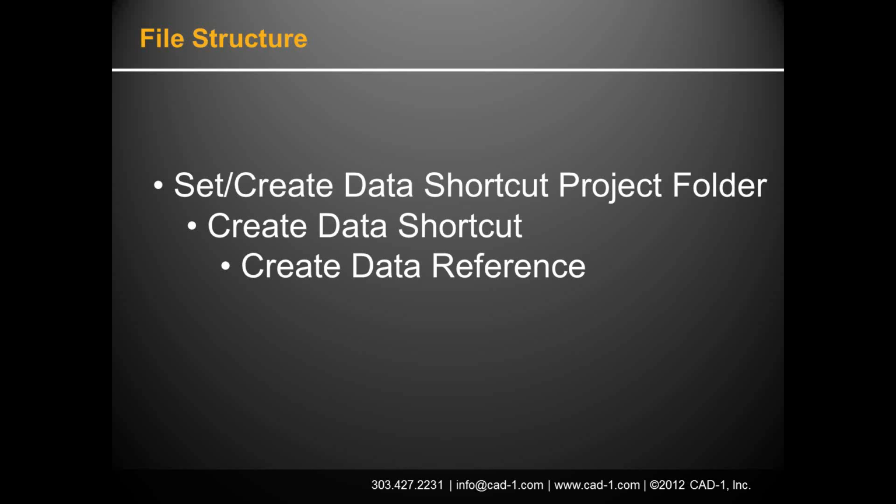Thank you. Now, like I said before, prior to creating the data shortcut, I need to set and create the data shortcut project folder. This is where my shortcuts are going to be stored on my network somewhere. It creates a little shortcut folder underneath the project folder, and that's where all my shortcuts go, and you'll see this here in just a bit.